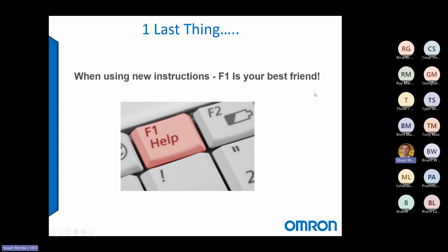And finally, one last thing, there may be some new instructions you're not familiar with. If you click on any instruction and press F1, it brings up a great instruction reference with examples, with variable clarification in both ladder and structured text. So very useful if you're working with new instructions to just hit F1 and read up on the instruction a little bit. Or if you're having any issues, that might be the solution for you.